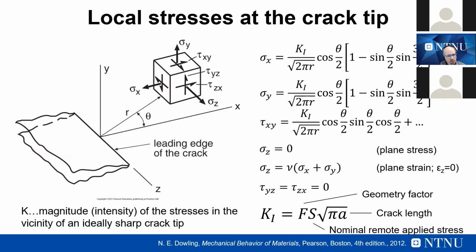And what is also important is that all the theory that we have developed for these modes of failure is considering linear elastic mechanics. So as you discussed yesterday with Professor Sedmak, the main hypothesis here is that the stress field close to the crack tip has to be linear elastic.